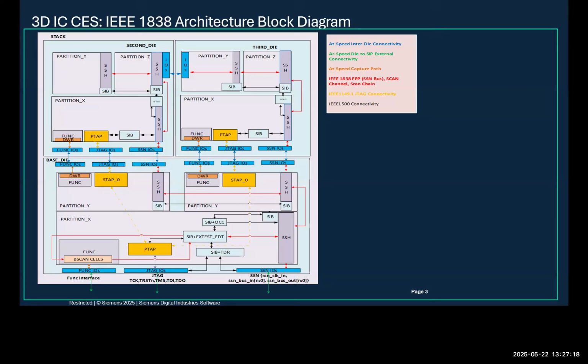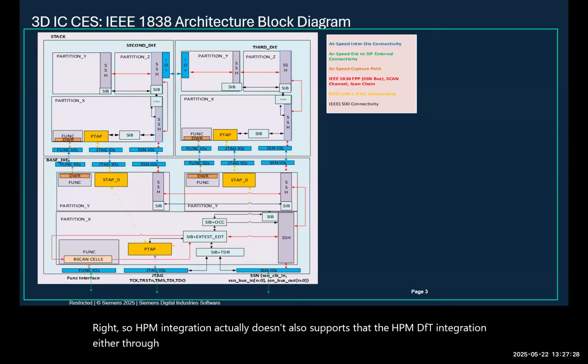Right. So HBM DFT integration actually supports either the tap controller or the IEEE 1500. But it is not methodologically aligned to support the 1838.